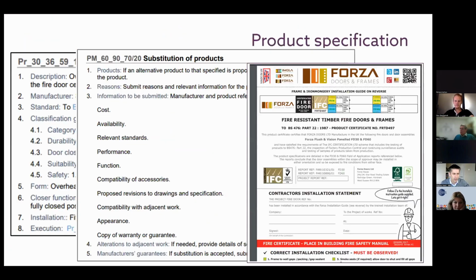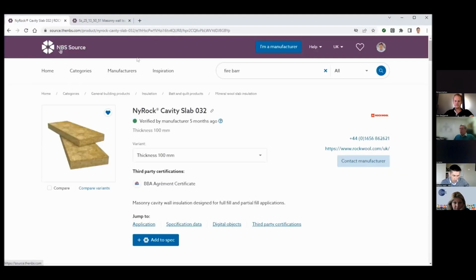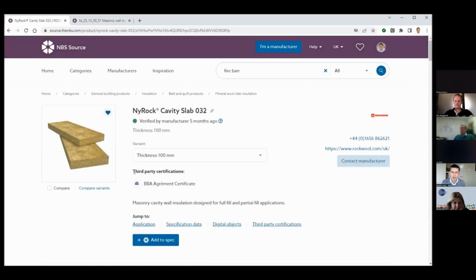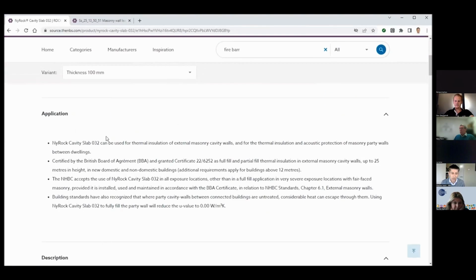Let me just jump right at the end where we had the product information sequence. For this particular product you see on the screen, we've got a little GUID behind there, that little link that you can copy with the clipboard, and you can include those GUIDs in a barcode or an RFID. We're going to keep that product information live over the years, and say when it's been replaced, keep a copy of things like the O&M manual.